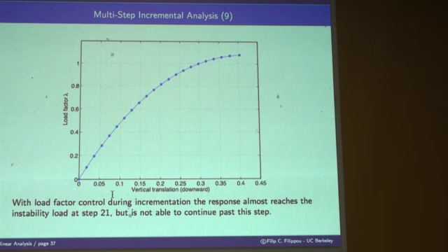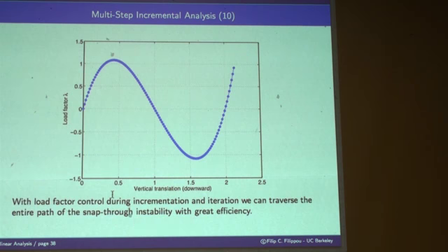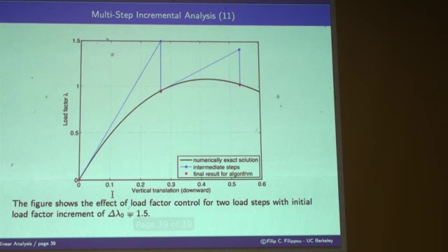So typically we assume we multiply lambda times P. That lambda has to be adjustable. If it is adjustable, I can walk all the way up to the top of the hill. I can determine the ultimate load. Very safe. I cannot just go beyond, unless I also have control past the peak, which displacement control ensures, arc length method ensures. And in that case, you see what happens, right?